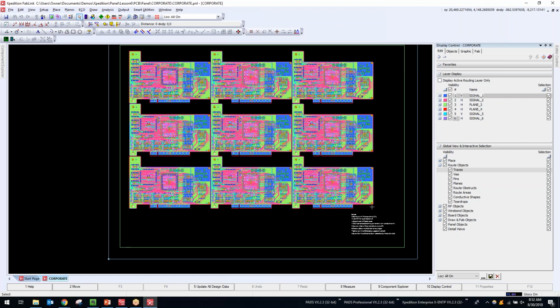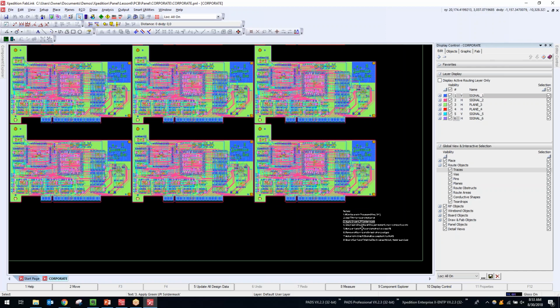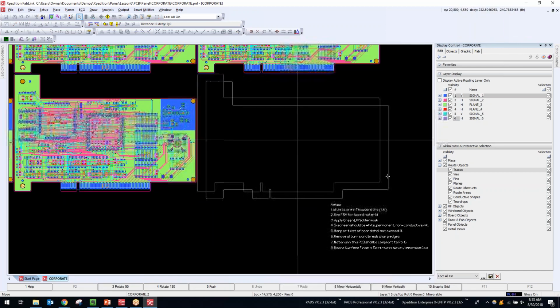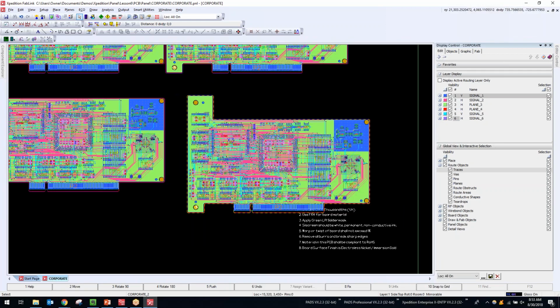So I know a lot of people in the panelization process, if we're doing panelization in-house, they like to use tools that read in the board dimensions, and then say how to best place your boards on the panel and allow you to get the maximum yield per panel. If you'd like to do that, once you have arrayed the different objects, I can actually go ahead and move this board and change the rotation if I'd like.